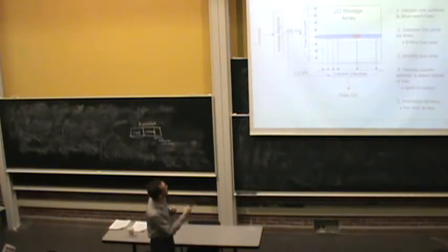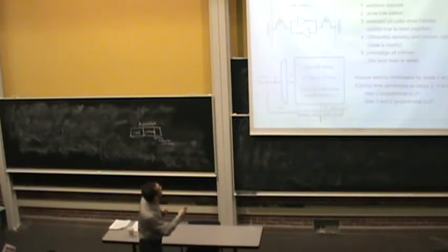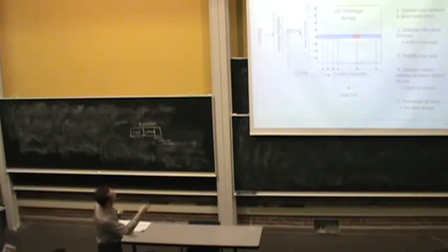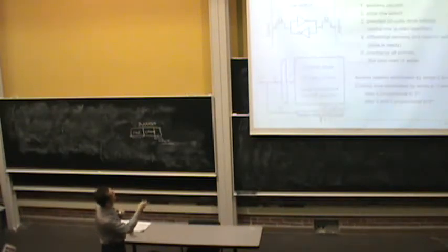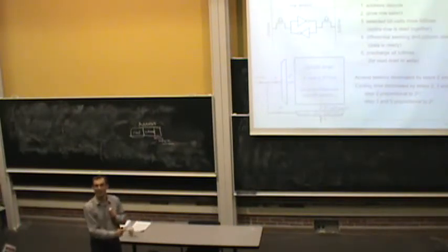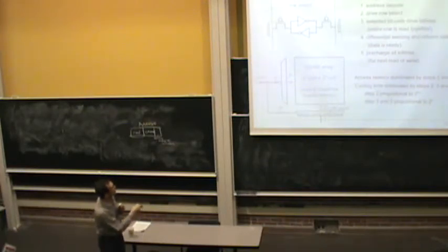If you look at SRAM, basically these cells consist of these. And this is a typical SRAM array. Why do you have this two-dimensional organization? Why not read only one column? Why not have only one column? Well, you decide this organization to minimize the overall latency.